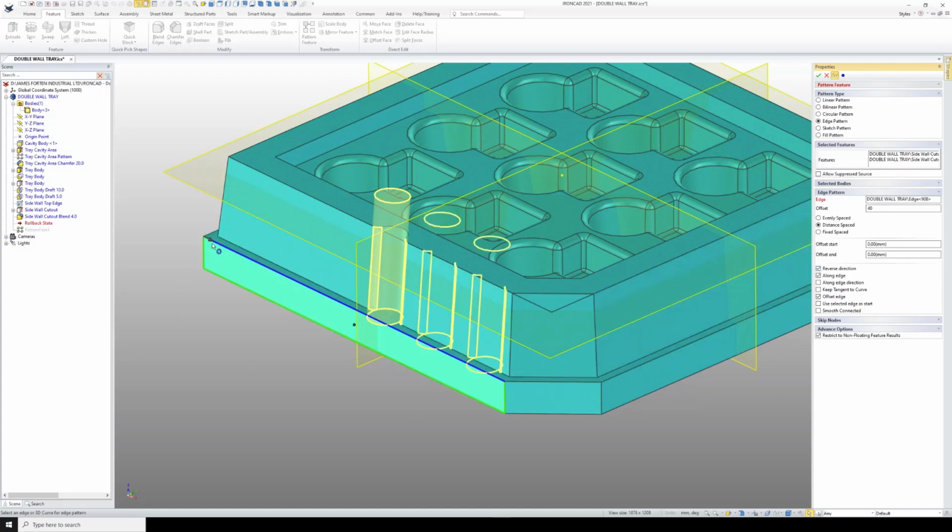You can see the arrows change now. So in that edge, I was just wanting to select a direction. And now I want to control how closely my cutout gets to the edge. I don't want it to this edge here, this point. I don't want it to be any closer than 40.